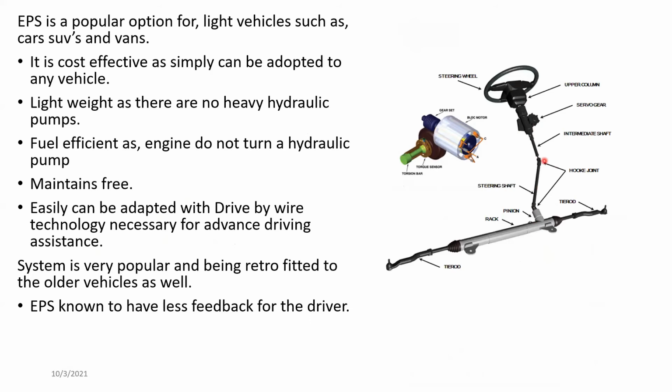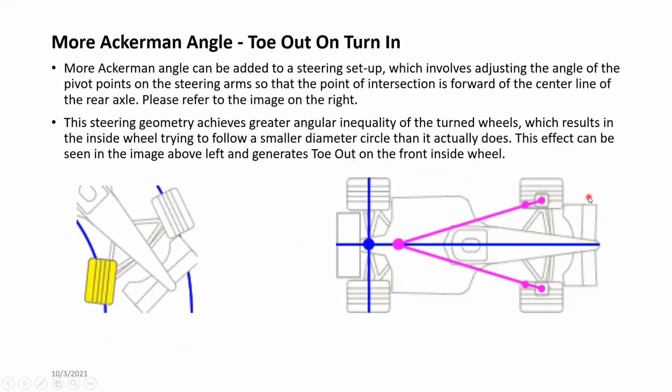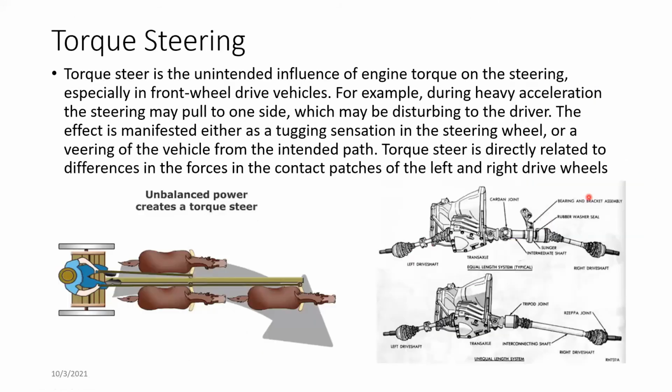The reason is that the steering system is designed to collapse in an accident. In an accident, these hook joints allow the front steering rack to move without moving the steering wheel and the column. That provides the safety cell for the driver, right? Safety cell for the driver.